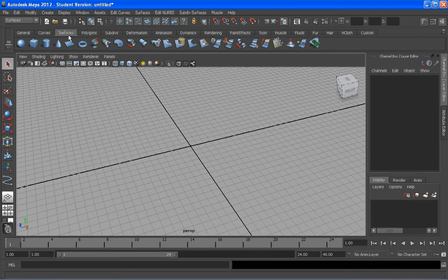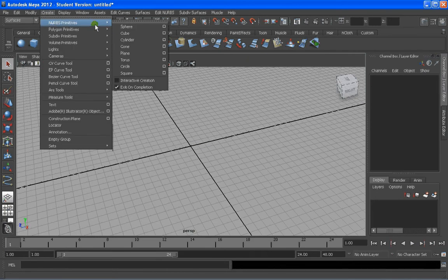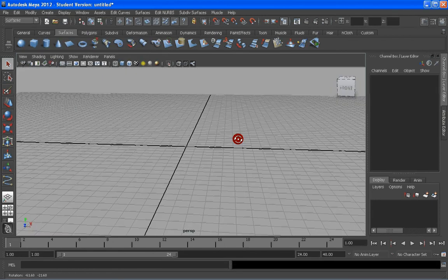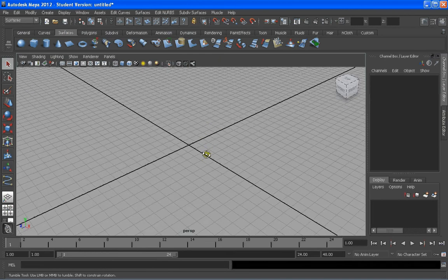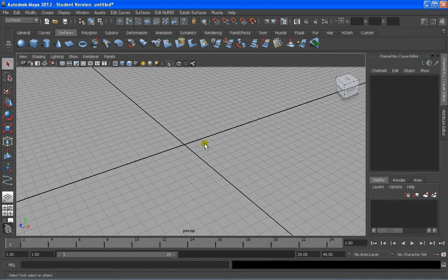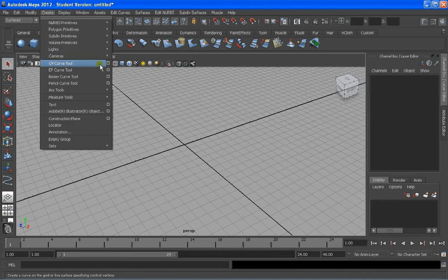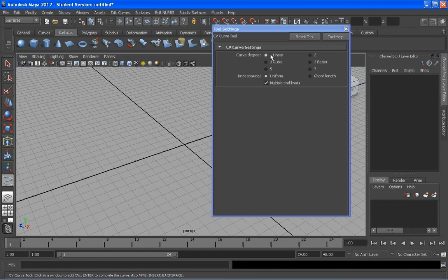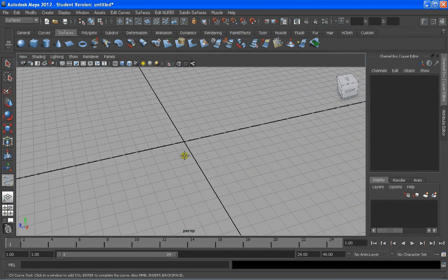Okay, another thing. Let's go to Create. As we know, in NURBS primitives, we have this unchecked. So whatever I create, a box, circle, it's going to create it in the middle, related to the main axis, and symmetrical, and one unit measuring. Okay, Create. We're going to do a CV Curve. Options. We want the 1 Linear checked for the degree. It's going to create a polyline versus a curve, which will be the 3 Cubic option. And we're going to snap to the grid. X, as you know, this guy highlights while we hold the X button, and we're going to create from here to here, which is 2 units length.